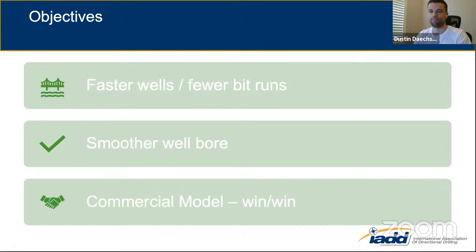Brandon, thoughts? Yeah, I mean, this is a complicated problem because the cutter and the bit alone in that system are so interdependent on how we lay out the cutters, what the back rake and side rakes are going to be, cutter diameter, cutter density, chamfer angle. It's almost infinite the number of factors you can put into just thinking about the bit design and the cutter design itself. And so our approach generally is to work directly with a bit customer to customize our product, to work with them together as a system, and to go through that process iteratively.